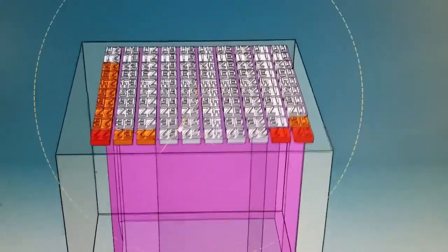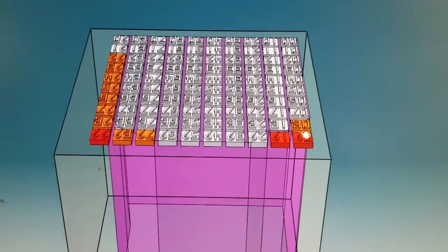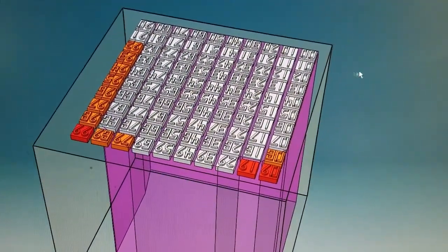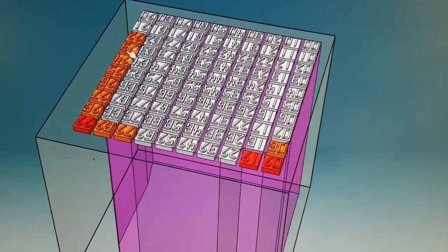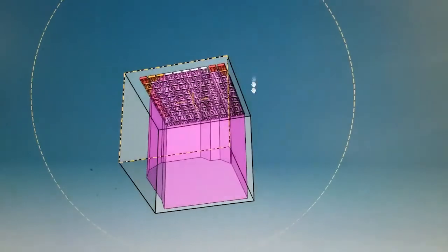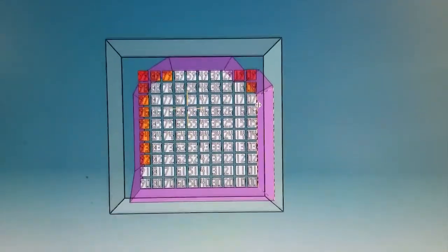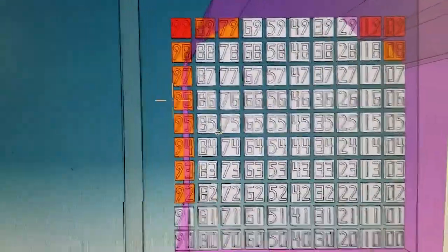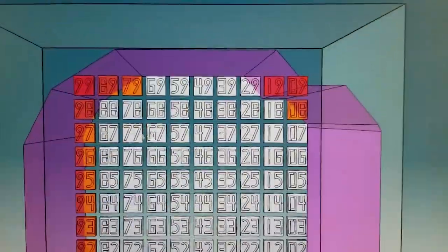What I won't post is all of the colors and all the changes, because your bed may be different than mine. You have to use this information: check all of the pieces that came out, and then identify which areas were bad. Then I made this boundary volume, which is easier to see from the bottom, and this is basically where it's safe. Anywhere that it was orange, I went through the middle, and anywhere that was red, I just completely avoided.